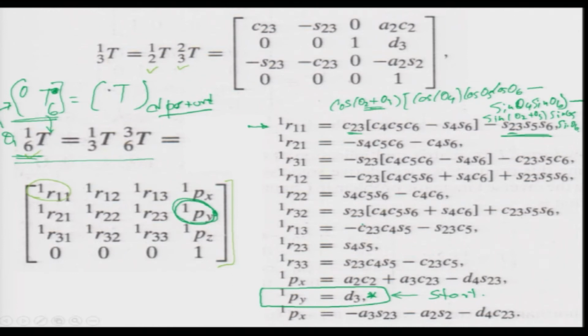If I want to remove theta 1 from here, I take the first matrix, T 0 to 1, take its inverse and bring it onto that side. Now, if I bring it onto that side, what it essentially means is that I have 1 to 6 on this side now. 1 to 6 would mean that the variables are now theta 2 to theta 6. Theta 1 has gone this side now. That is the basic philosophy, or the process, for trying to solve for the PUMA.